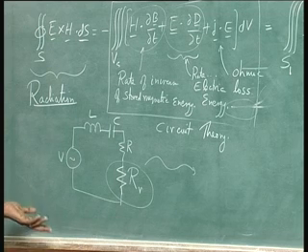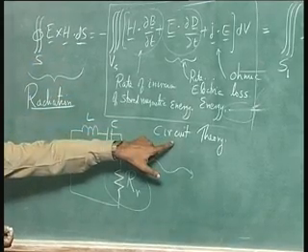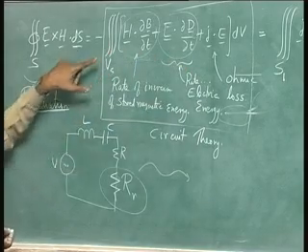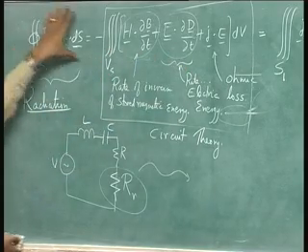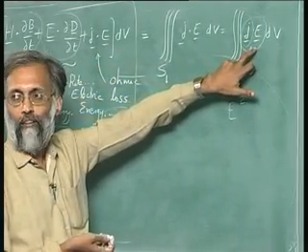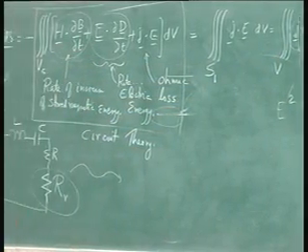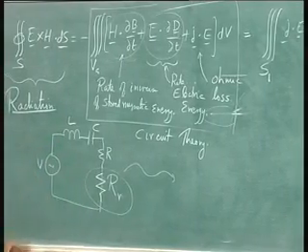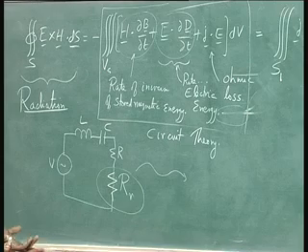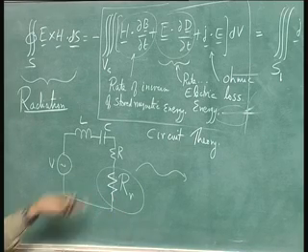They are not really true anymore. The moment you have this term, circuit theory has failed, because circuit theory is only this side. But we fake it. We say that this piece can after all be modeled by this J dot E term, and therefore, from the circuit theory point of view, we will just add a new resistor. It is a frequency dependent resistor, it is a resistor with very strange properties,